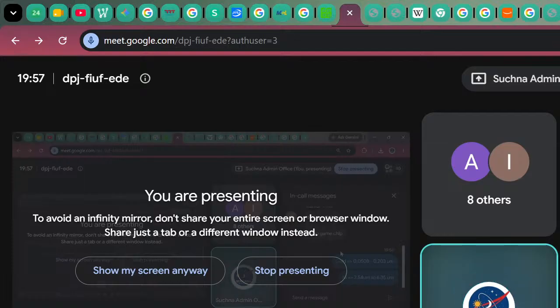No, you are not allowed to put the thickness of the nickel greater than 6.35 micrometer. It should be greater than or equal to 2.54 and less than or equal to 6.35 micrometer. You are not allowed to put even 6.36. It should be less than or equal to 6.35.